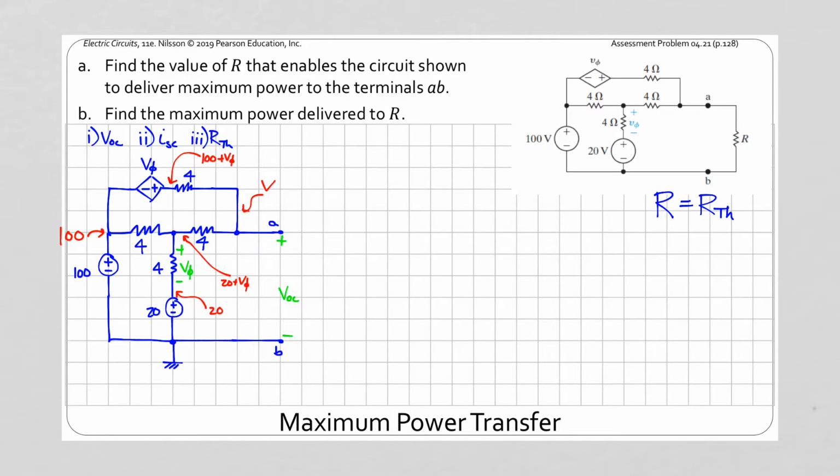And then I want to look at the currents that I have flowing. I'm going to have a current flowing this way, and a current flowing that way, this way, and that way. And so right now I have two unknowns. I don't know what V phi is. I don't know what this V is either. So I'm going to need two equations to solve those two unknowns. My two equations will be a node equation right here and a node equation right there. Those are the only two independent nodes that I have. Everything else is connected by voltage sources, and so those are all referenced to ground, so we have values for all of those. So I'm going to write node equations for this node and then for that node.